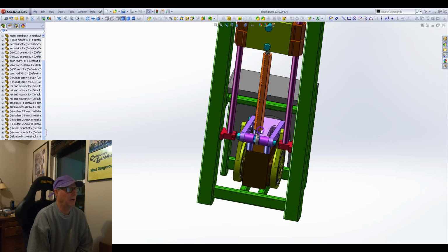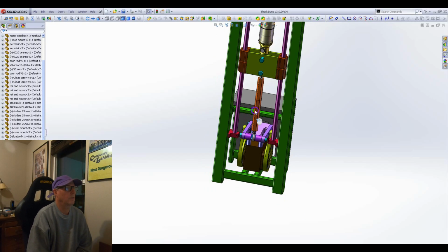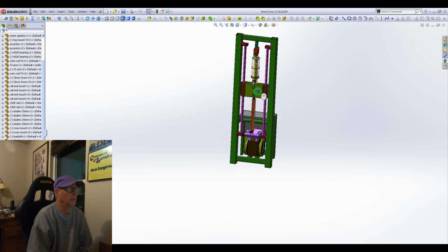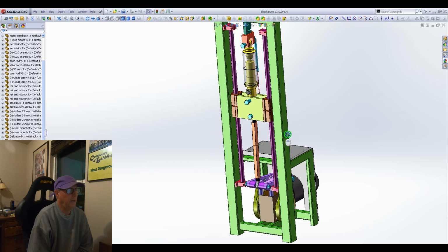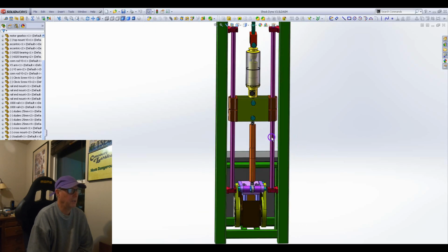The purpose of this rod is how I take up the adjustment, with a left-handed heim on this end and a right-handed heim on the other. On this end you can make small adjustments, and then for big adjustments you could get a piece of hex bar, and you could have a 2-inch one and a 3-inch one and a 5-inch one and a 12-inch one, whatever. That would allow you to run long shocks and short shocks. And then I found these linear guides. This is like a 25 millimeter guide rod.